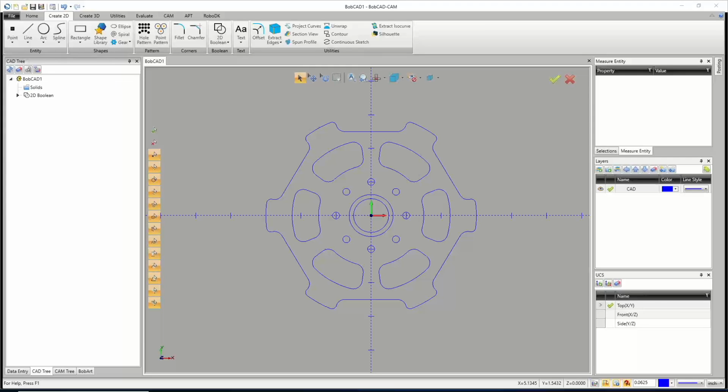So, all right, let's get into this. As of now, the big things that I need to know for this drawing are really the hole sizes for everything. So we have an outer arc. We have an inner arc that makes this slot. We have a 1 inch inside hole here. And then this inside lip to this slot is going to be a 3 inch diameter arc. Then we have a 4.5 inch diameter arc. And then we have a 6 inch diameter arc.